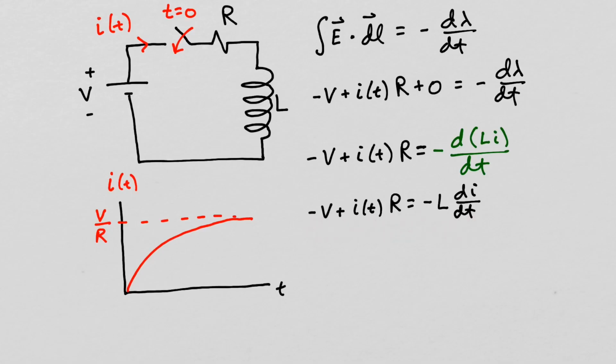This equation should look familiar to you, which previously you would obtain using Kirchhoff's voltage law, and this term as the voltage associated with the inductor. But if the voltage is really the integral of E dot dl through the inductor, and the inductor has a negligible electric field in it, the voltage obtained by integrating E dot dl is really 0.